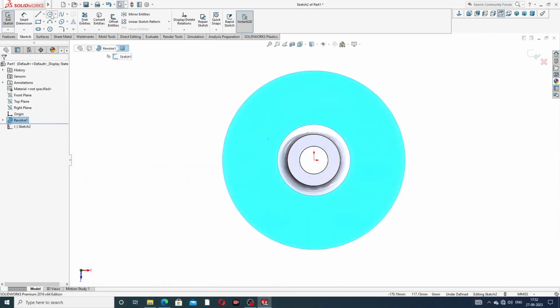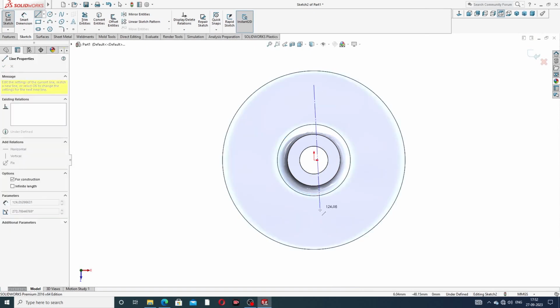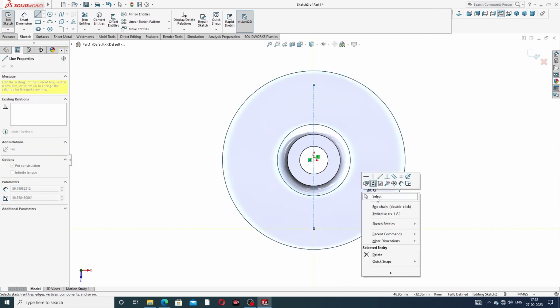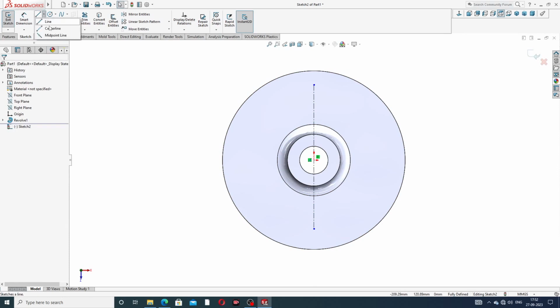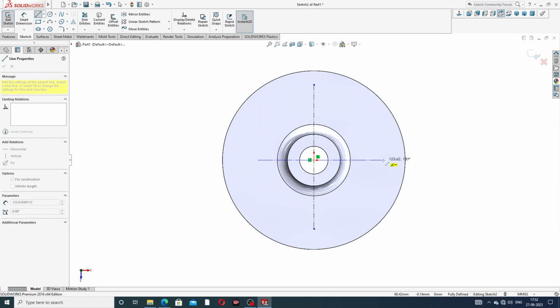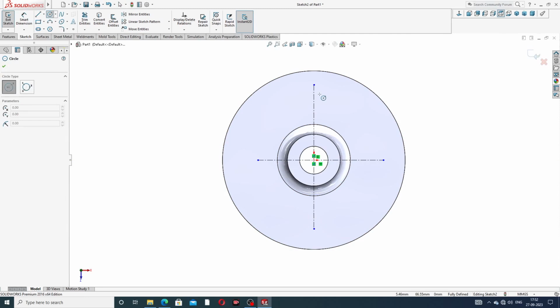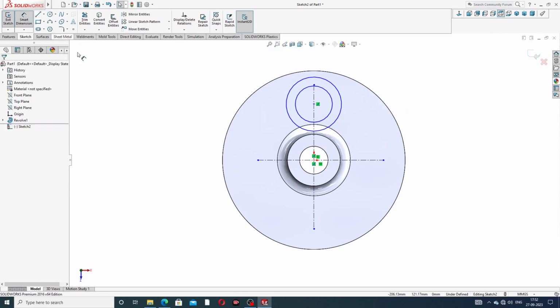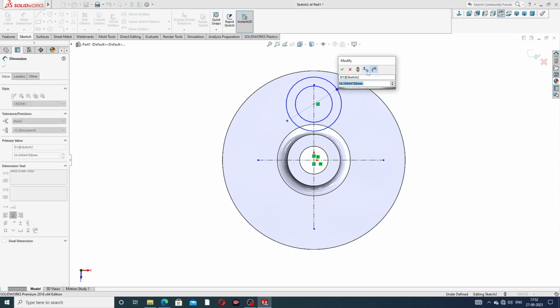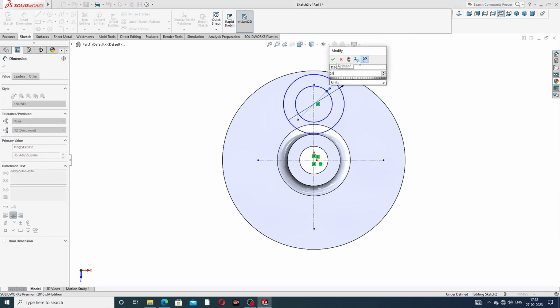At first draw a reference line, again select, okay, both reference lines are drawn here. Okay, connect to this, the reference line is very important, and draw a circle. Two circles are drawn here. First is a diameter of 60 millimeter, and second is a diameter of 24 millimeter.